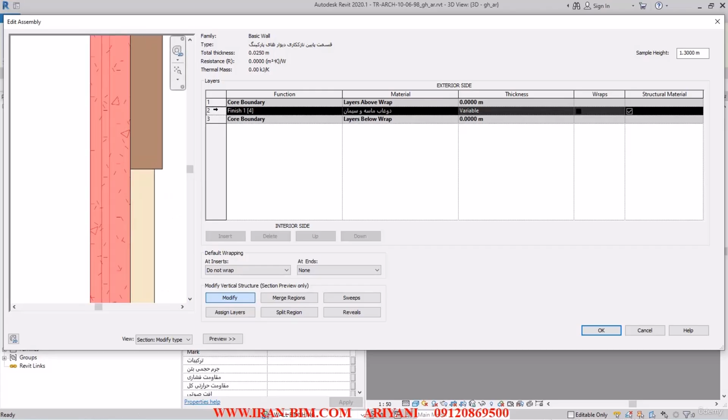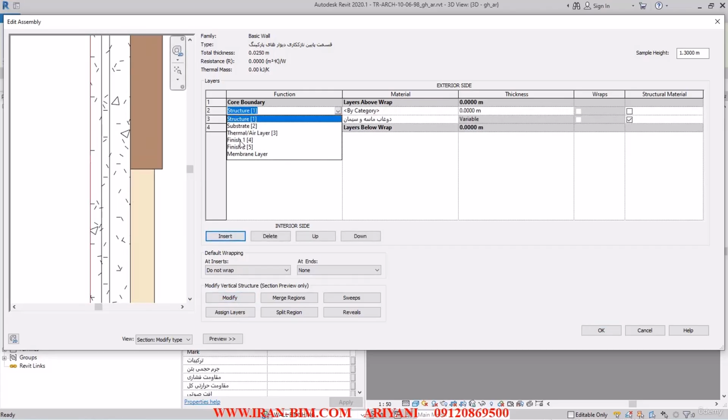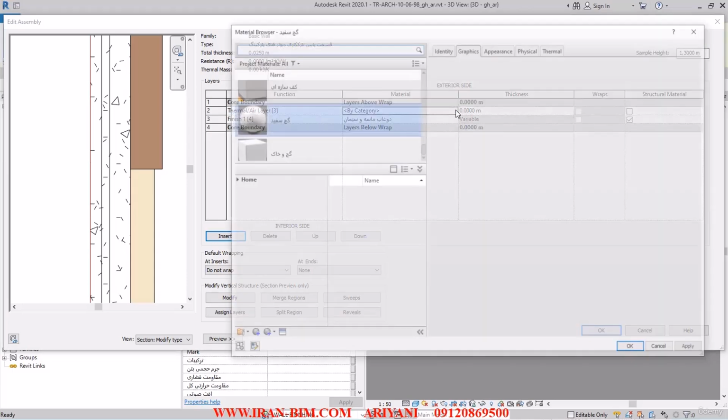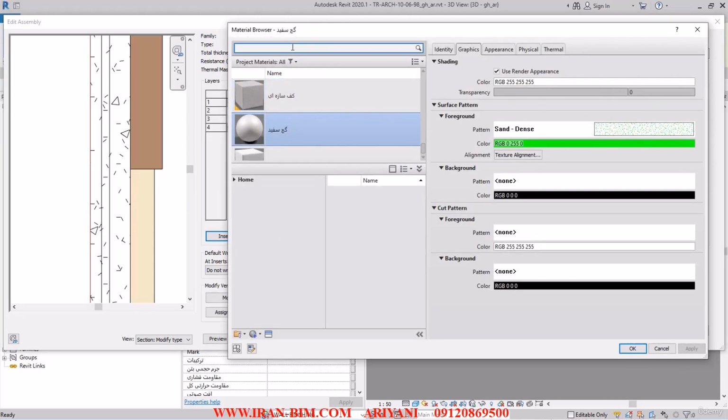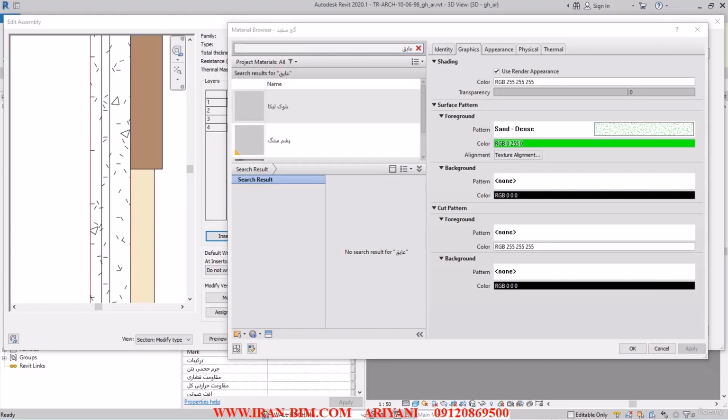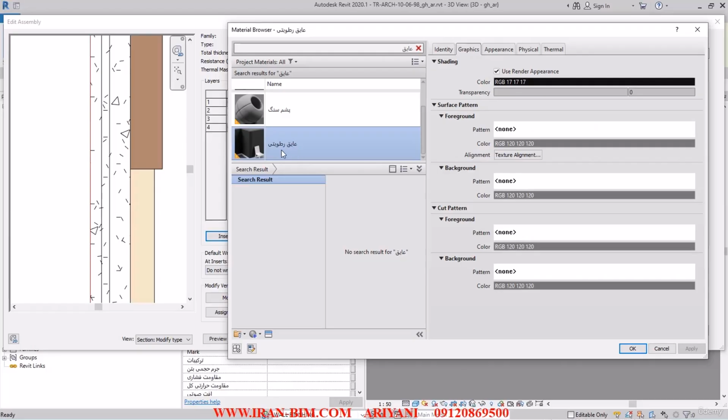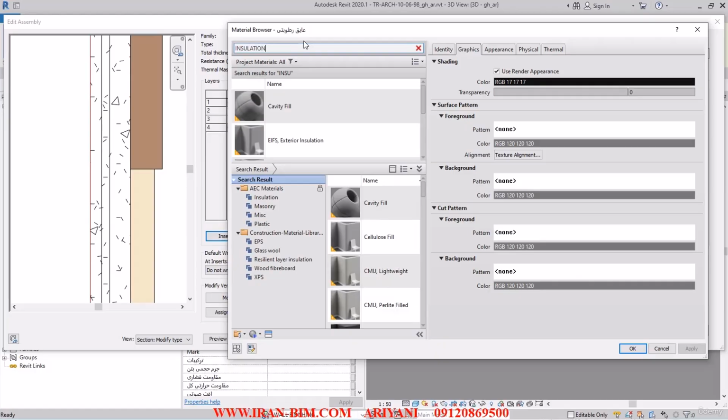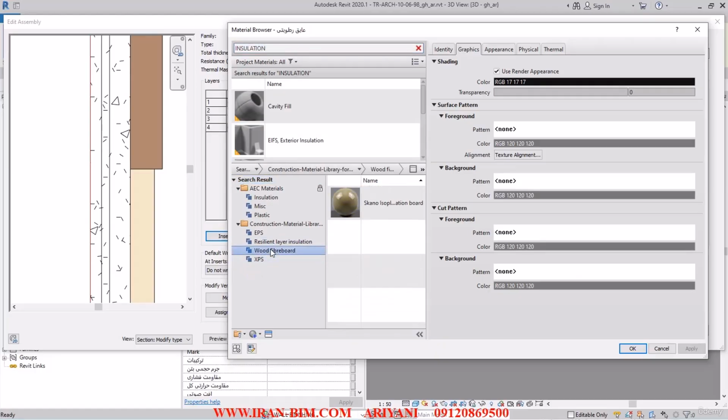So I'll select this layer, and then I'll set a new one, and then I'll put this under the fourth finish type, or maybe this thermal air layer. After doing that, I'll open up the material browser, and here let me just type in insulation. Let's see what we have. So according to the joinery chart that we had, the moisture-proof insulation has 3 layers of bitumen and 2 layers of matte. So let me just search for insulation in the box here. And let's see if we can find anything useful.